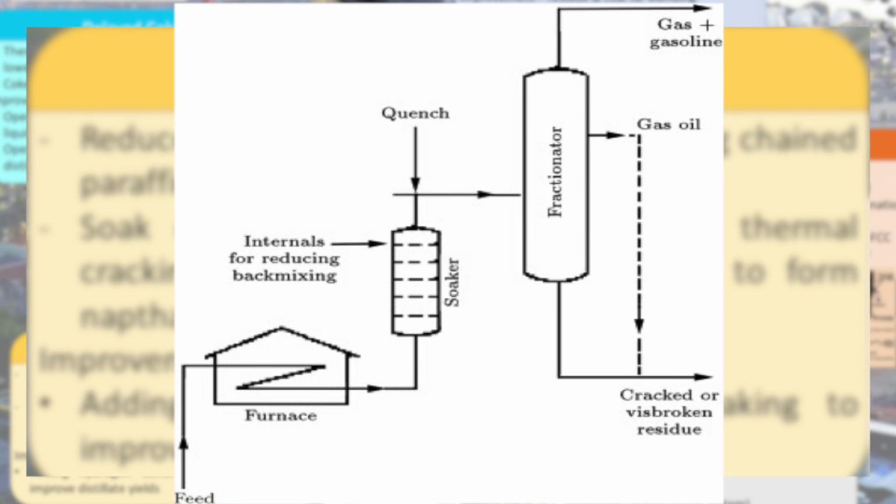cracking temperature. Furnace effluent is sent to the soaker drum, where most of the thermal cracking and viscosity reduction takes place under controlled conditions. The pressure in the soaker drum can be adjusted, which results in a change in residence time and the amount of heavies that reside in the liquid phase. This flexibility in pressure provides the possibility to reach optimal selectivity.